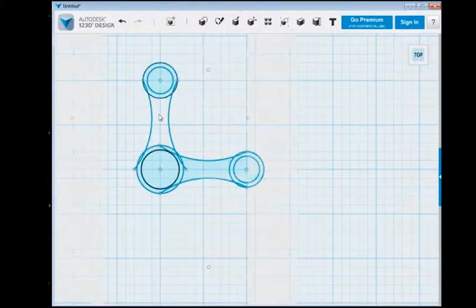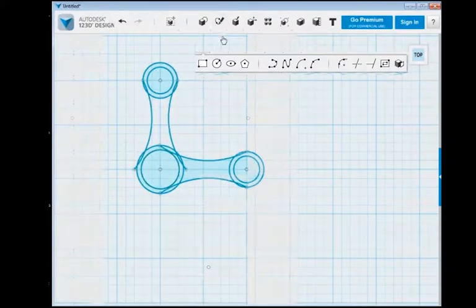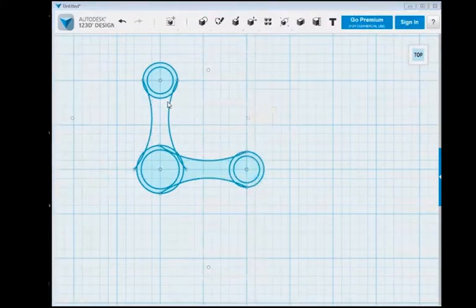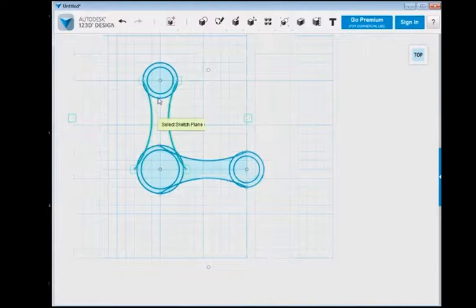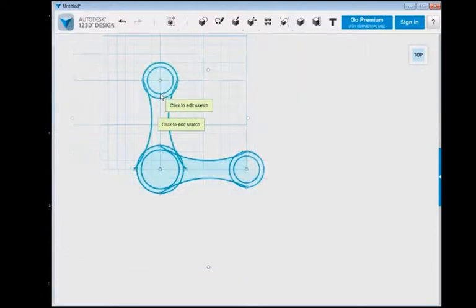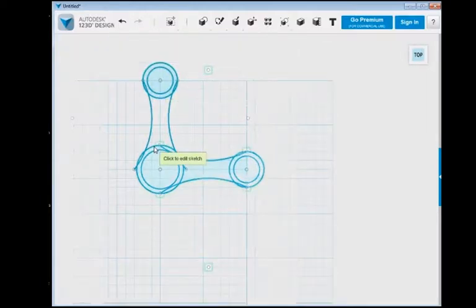Now this is a little bit of a problem because this sketch is complete, this sketch is complete, but in order to connect the arms, I'd have to make a line from here to here and from here to here. Whereas on this sketch down here, everything is attached. You'll see that because it's all blue. So if I go to my trim tool and I hover, only this circle selects, but notice how it's entirely there.